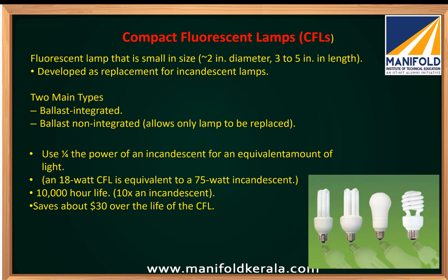Compact fluorescent lamps, CFL. So fluorescent lamp that is smaller in size, that is 2 inches in diameter or 3 to 5 inches in length, developed as a replacement for incandescent lamps. There are 2 main types of CFLs: ballast integrated, ballast not integrated. Understand?